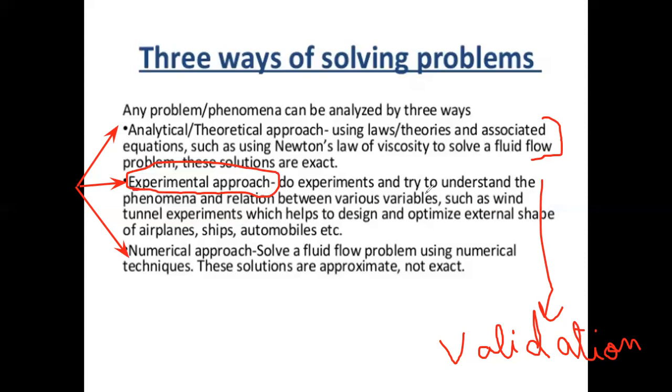To help me know if my CFD model is working or not, I can compare the results I get from CFD with the experiment. This is called the validation procedure. If I am able to reach a relatively very small error, I can calculate the relative error. If it's of order less than 10%, I can say that I validated my model with experiments.